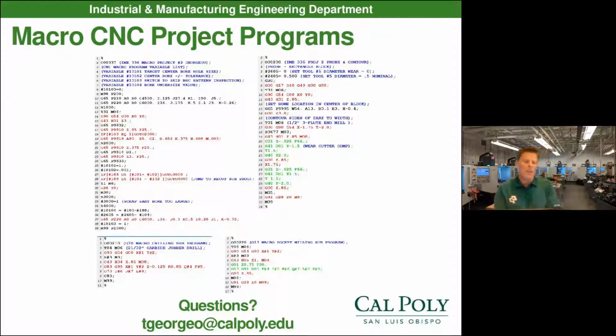There's also been a question from Christopher. He asks about some people criticizing using the same machine for cutting and inspection. Can you comment on this? Yes, I've heard about this for the past 25 years since I've been a student in manufacturing engineering: you can't cut on the same machine. Well, what happens if you calibrate the machine against a standard, and you know that it's coming out to the right size? Another step you could do would be a gauge R&R study, a gauge repeatability and reproducibility study on your probe on your machine.